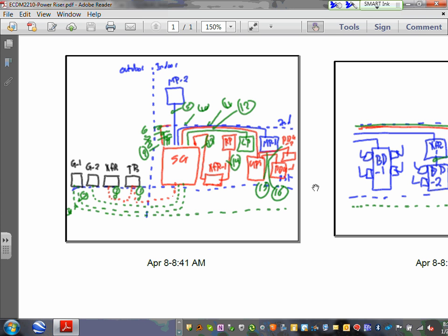And then inside the switchgear, Karen, we're going to take a feeder and feed the mechanical panel 2 in the second floor. We're going to take another feeder, feed mechanical panel 1. Then we're going to take a feeder that feeds receptacle panel through a transformer, lighting panel, UPS, PDU, and PDU1 and PDU2 here. And then I don't know if you guys can see, this is continuation of the bus duct.